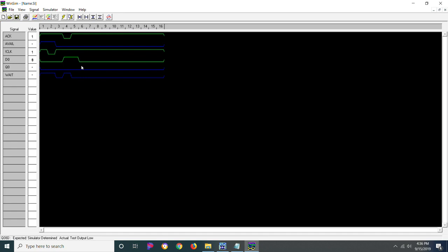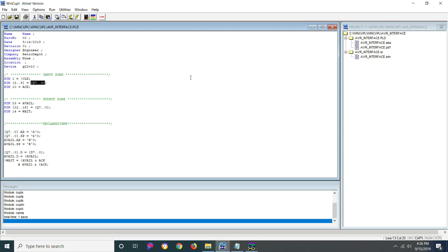So for an example, you have that output enable, and let's say you just needed to store an 8-bit value to read back at a later time. 1 byte of memory, if you will. So you would do something like this, where you actually had D 7 through 0, and you latch that data in, and then with another chip select, you feed that back through and connect it to the output enable, so that whenever you have a certain address location that you're reading from, it will trigger that output enable and stick that data back onto the data bus from Q7 to 0.